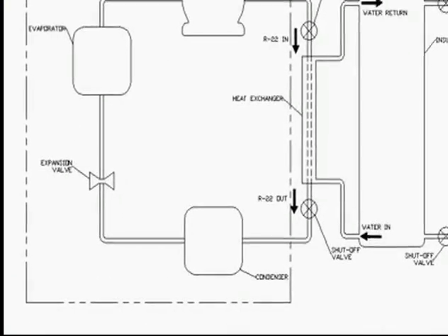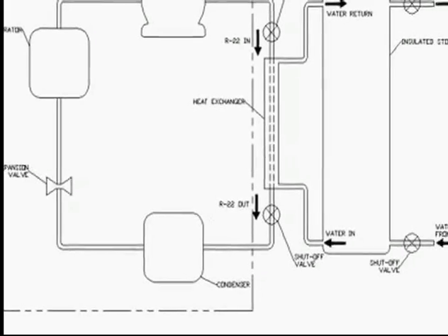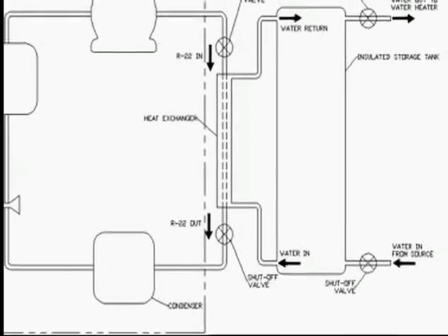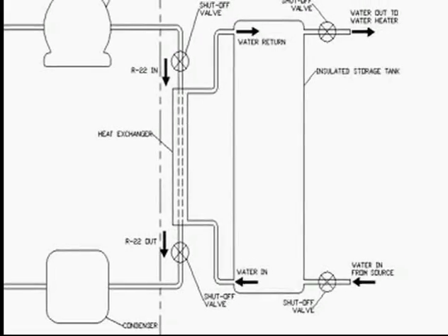The condenser will lose the heat to the outside. We are saying instead of losing this heat as waste to the outside, we're going to recover it and heat water with it. So we're going to bypass this condenser and go from the compressor to the heat exchanger and heat the water with it. So in the heat exchanger, water is heated by the passing superheated refrigerant.